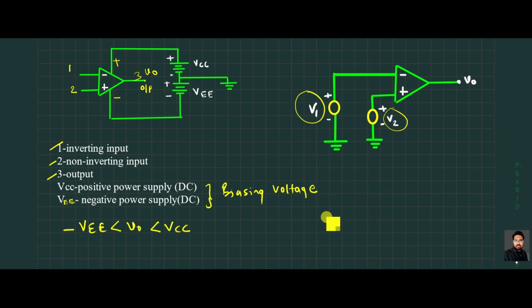So accordingly VCC is applied. Actually it's a symmetric power supply: plus minus 5 volt, plus minus 10 volt, plus minus 15 volt, plus minus 18 volt, and so on. There are limitations according to the manufacturer.